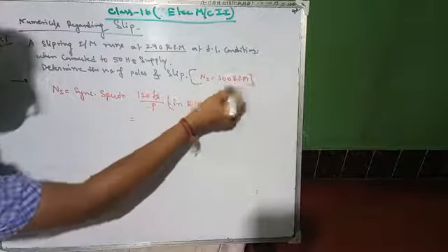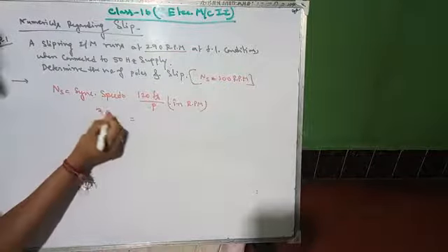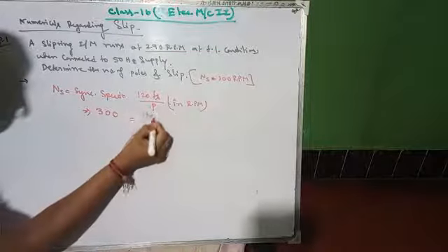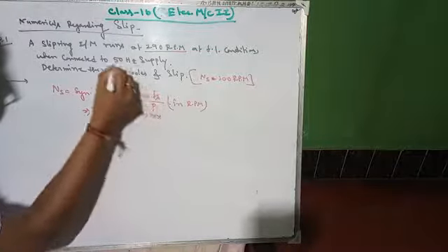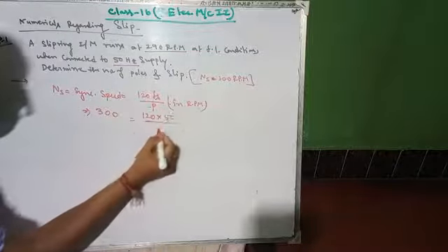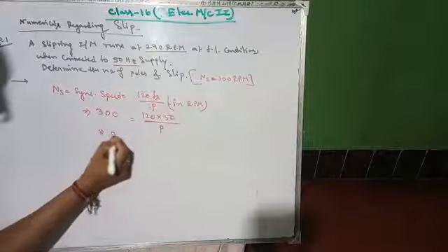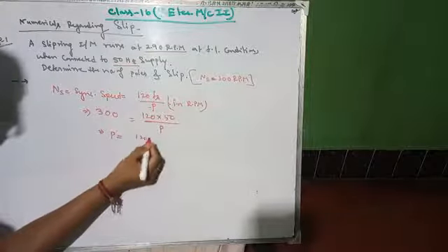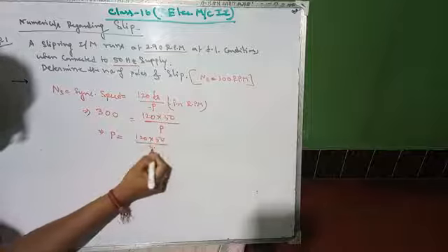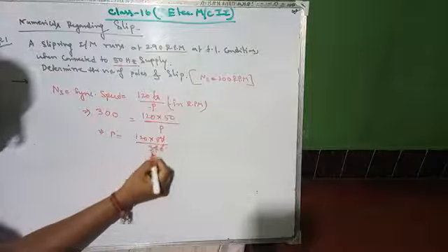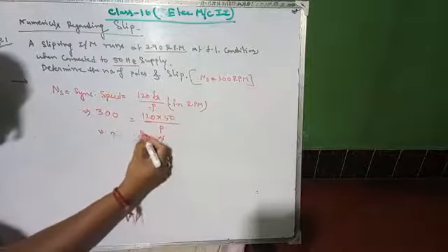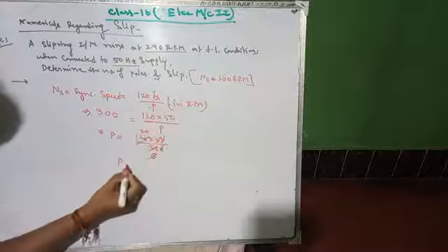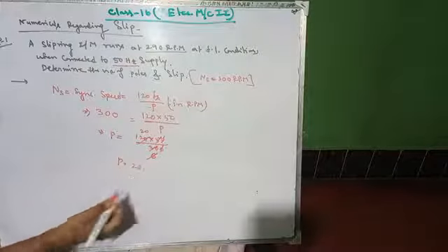It is given to you, right? So 300 rpm is given, 120, and fs equals supply frequency 50 hertz, and there is an unknown number of poles. So pole you have to find, right? So your answer will be 0 0 cancel out, 5 into 6, 6 into, that means how much? 20. So pole equals 20. So 20 number of poles.